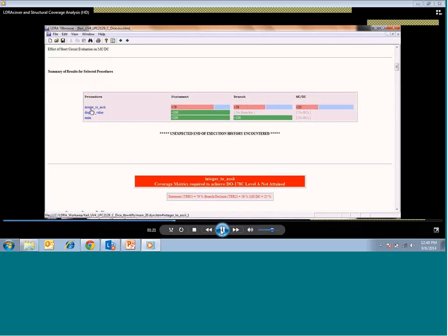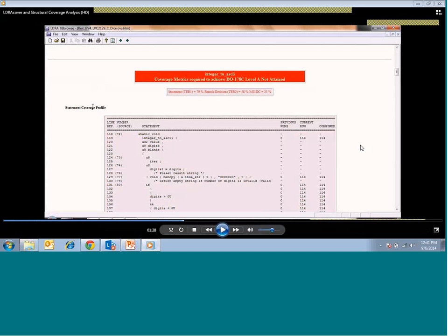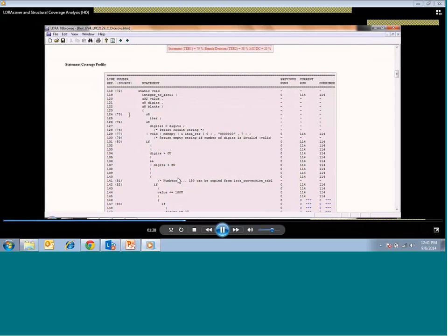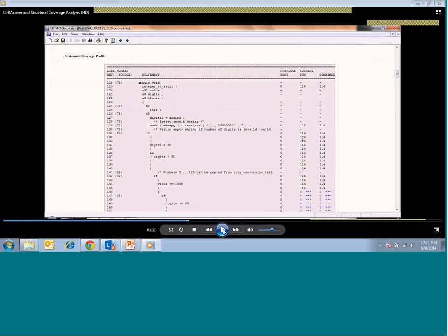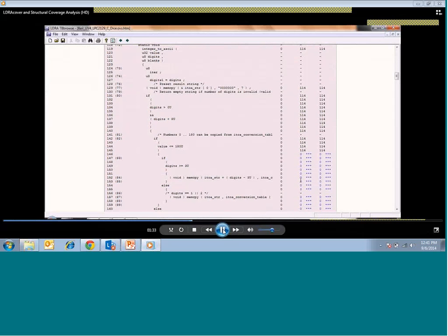And you can see that particular function, ASCII to integer, and the last 2-3 runs: the current run, previous run, and the combined run, how many times it has run with our simulator. It will show the number of calls, what statements are being called, and how many decisions it is able to drive, together with every line of the code. You can see the stars which are not executed at all, showing 0 times because the values it requires have not been attained.